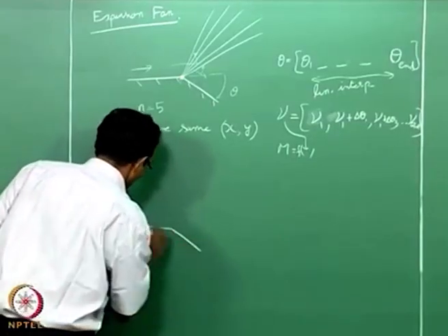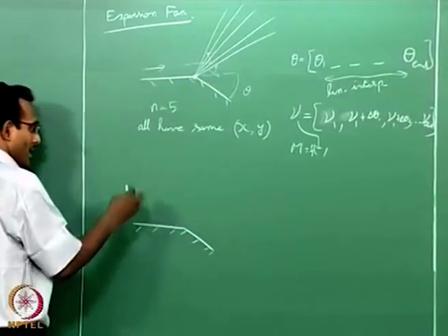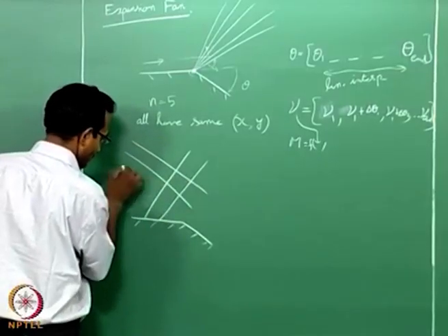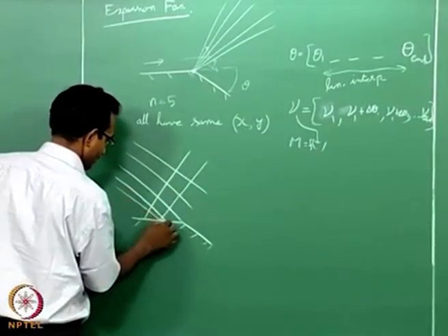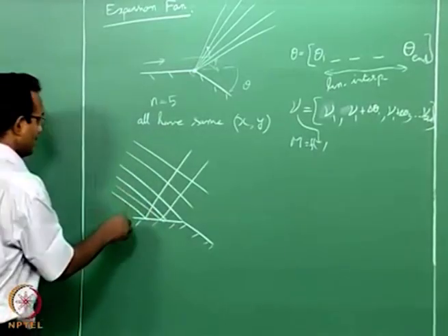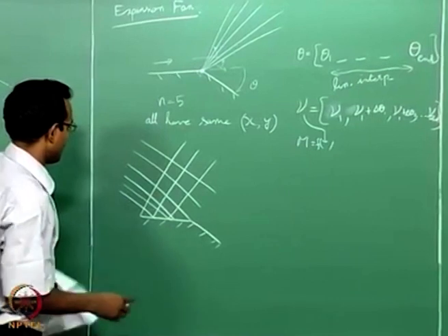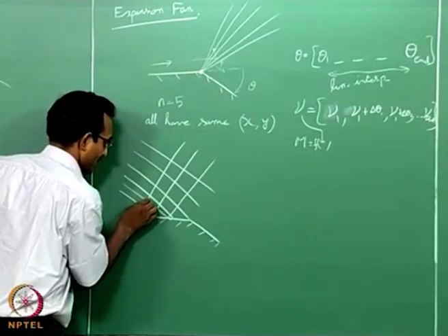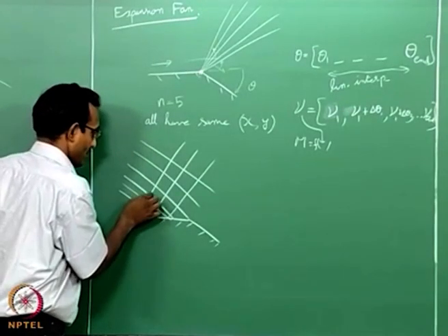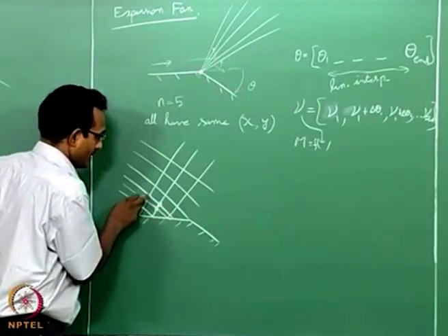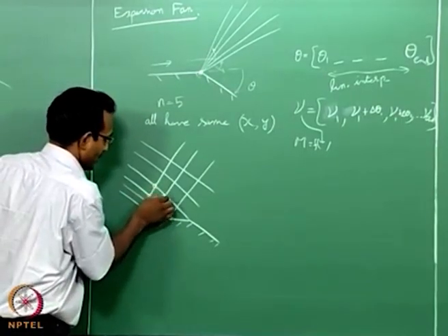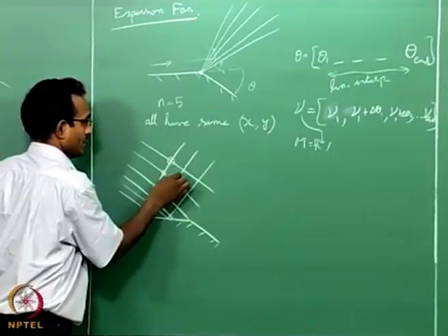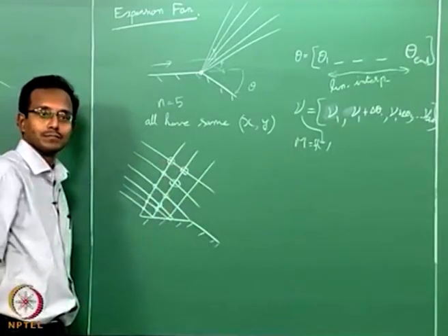If I have an expansion corner in my flow, and say I have solved like this till now. Somehow I got this kind of solution, that is, I knew some points already, and from there I got a wall point, from there I got this point, and from this point I got this interior point, from this interior point I got this interior point, these 2 interior points giving this, these 2 interior points giving this, and so on. Like that I can keep on finding, right.